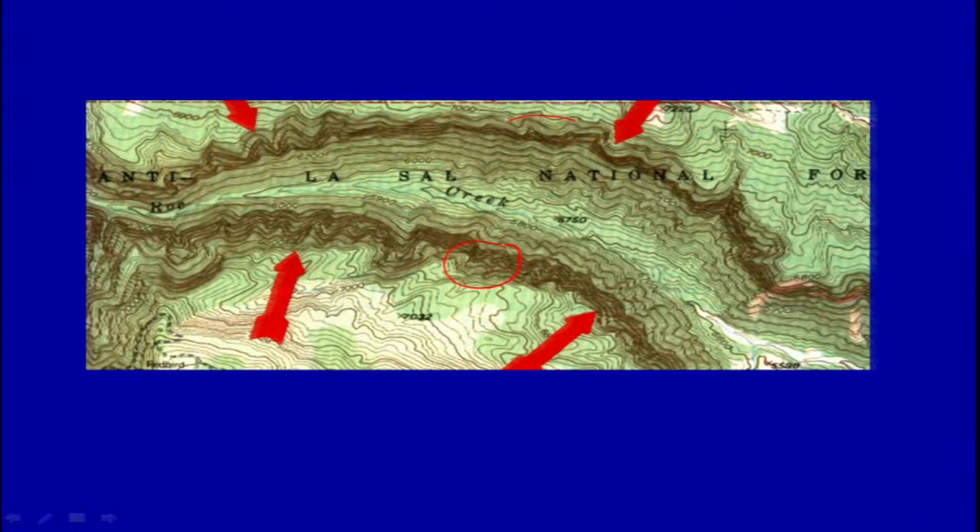Here also we are having very closely spaced contours in some places, and then it becomes wider here, and then it becomes wider here. Fine. So if you have to draw a cross section here, what you will find is something like this. Okay. You have a steep and then a broader, shallower here, and then becoming shallower here. So this is like in the valley.